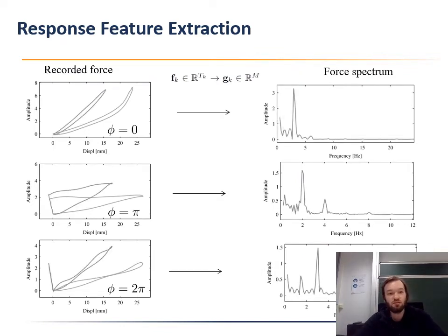Next, what we observe, we record the same shape of the material, but a little bit harder. For example, you can see the difference in the profile. So this can definitely indicate to you that this is a soft material. You see it behaves in a nonlinear way as the probes come very close to each other. But this one is more difficult. We stop our recording when the force reaches up to 7 to 8 newtons.